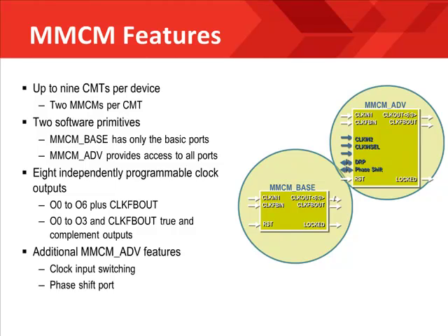Now, the MMCMs are located in the center column of the device. The PLL is designed to remove your input clock jitter. The MMCM advanced primitive supports the dynamic input selection and the dynamic phase shifting features.